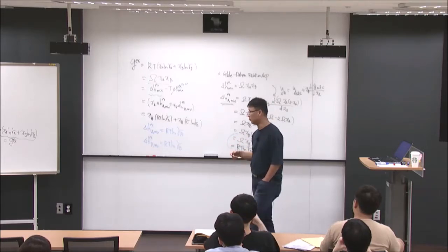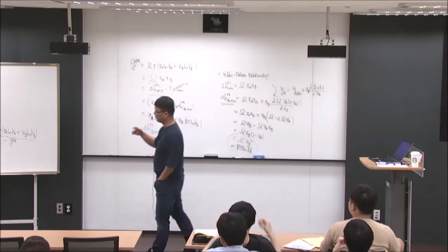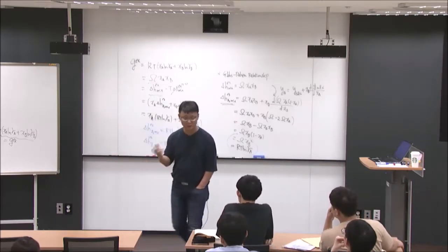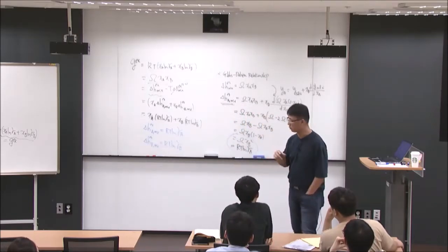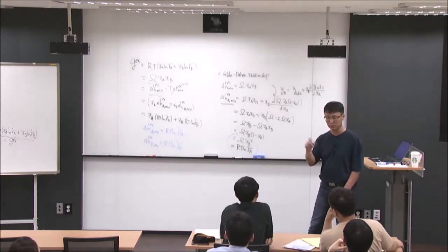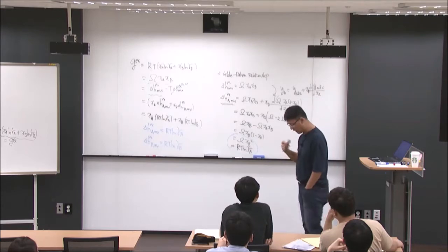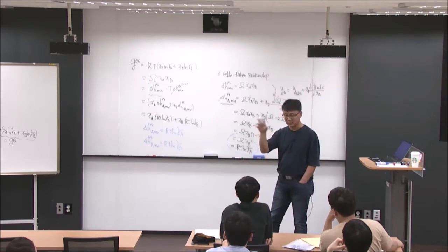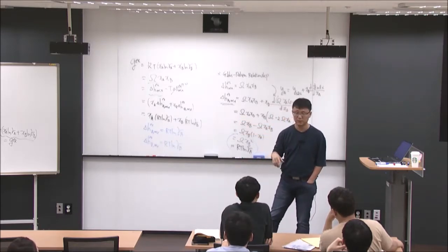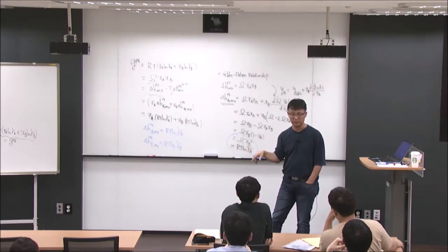And then we also derived the other very extreme case, called the regular solution. When it's a regular solution, there's interaction between the species, but that interaction only contributes from the enthalpy. There's no entropy contribution, but by the interaction between A and B species in the solution, it generates an enthalpy of the solution, and that could be negative or positive. That excess enthalpy term, the enthalpy of mixing, is expressed by omega XA XB, where omega is a constant term. It's independent of composition, independent of temperature. Okay?